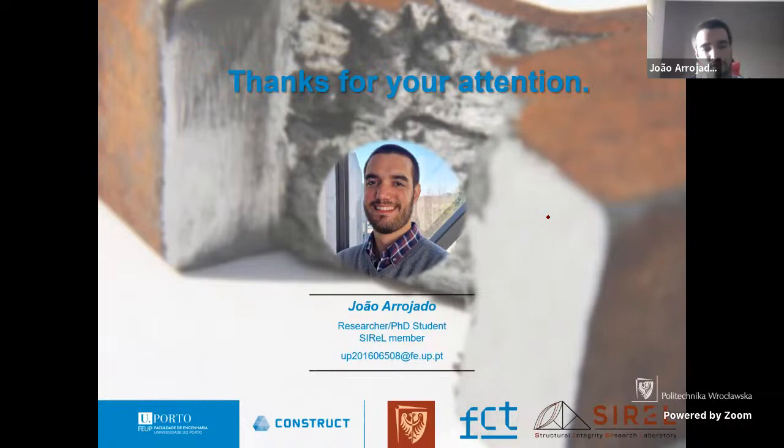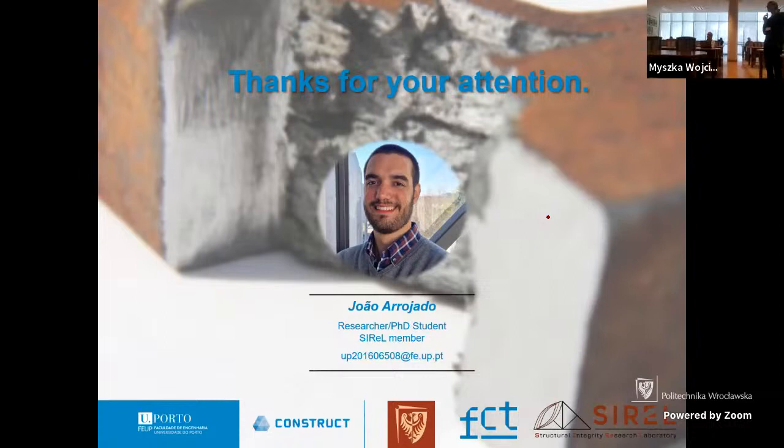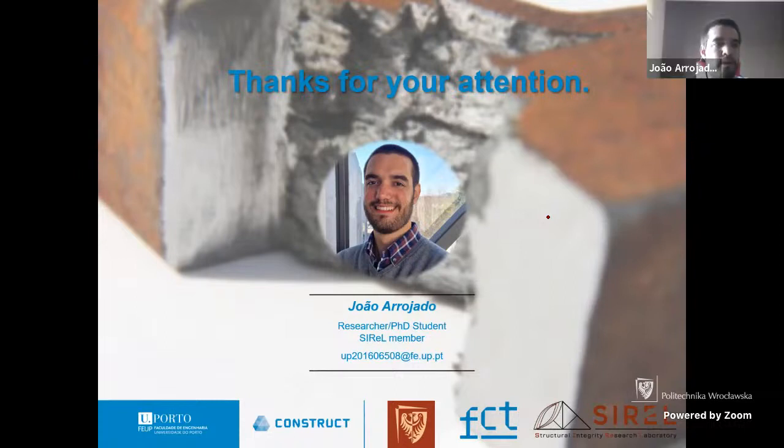Although this is not true for the puddle iron, because we know that puddle iron is very anisotropic. But for the sake of simplicity, I just considered the linear regime behavior without introducing plasticity. And the isotropic behavior was considered because we are in plane stress conditions. Okay, thank you. But in the future, it's good to improve the model, include plasticity, and also anisotropic behavior.